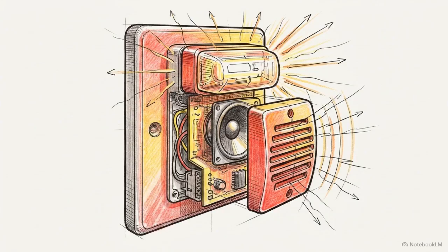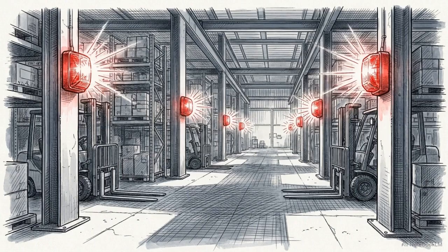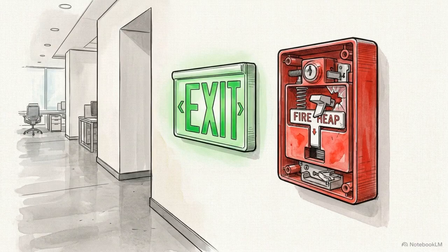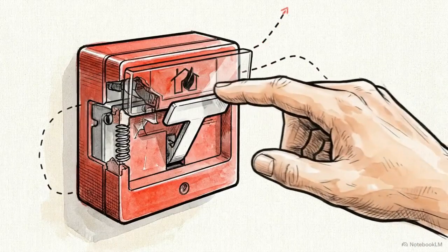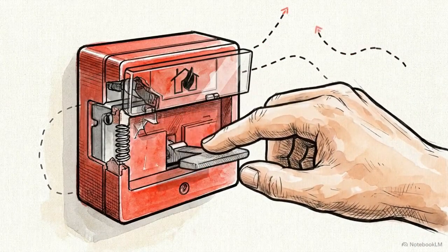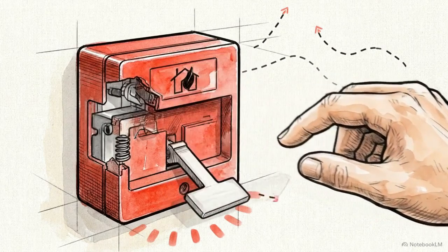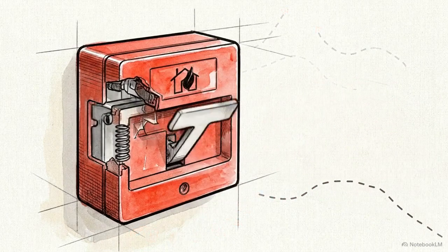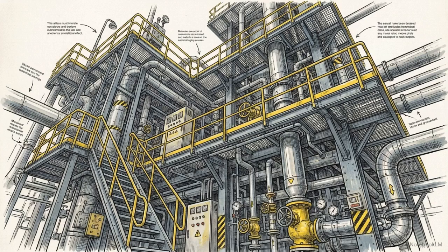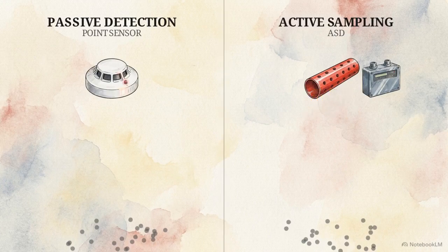When an emergency is verified, the panel activates primary output notification devices. These audible horns and visible strobes are engineered to operate seamlessly even during a total facility power failure, ensuring a universally understood evacuation signal. The system also accounts for human intervention. Manual initiating devices, like pull stations, are mounted near primary exit routes, so occupants can instantly trigger the sequence if they spot a hazard first. Even the most advanced sensor network is entirely useless without this redundant command center to process the data and sound the alert. Gathering that data requires capturing specific phenomena.